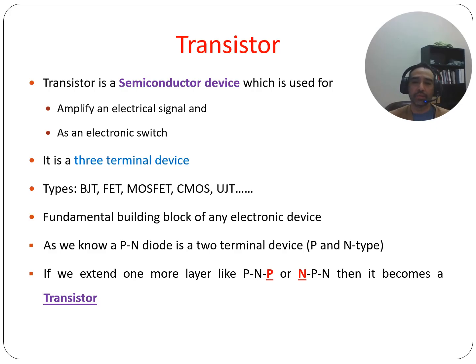The next one is a UJT. Sorry, getting word mix up here. Unijunction transistor, and this is a type of transistor with a single junction. And how does that work? Because it has three terminals. It has an emitter and it has two bases, a base one and a base two, and it's mainly used for triggering and timing applications. And so it's used in applications like pulse generation, timing circuits, because it's a very simple structure and it has very unique characteristics that allow it to do this.